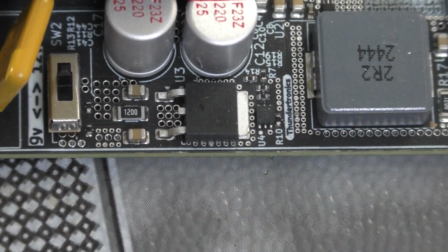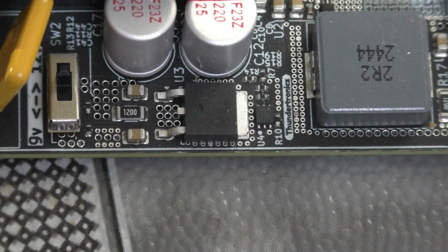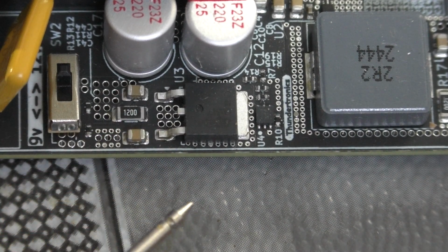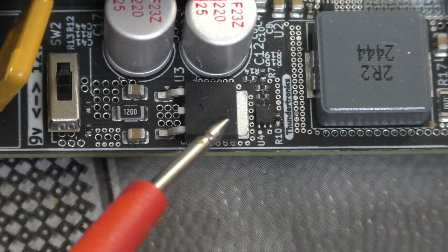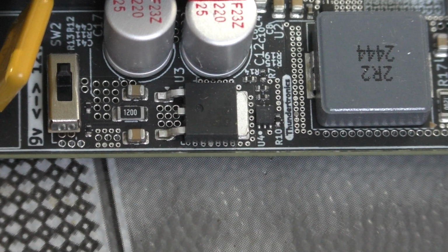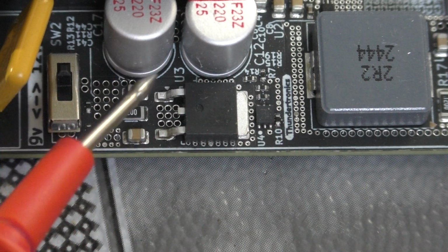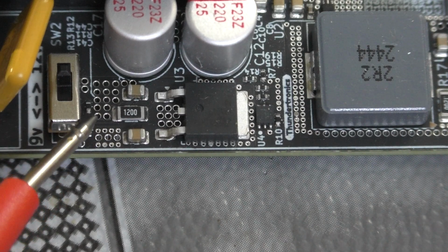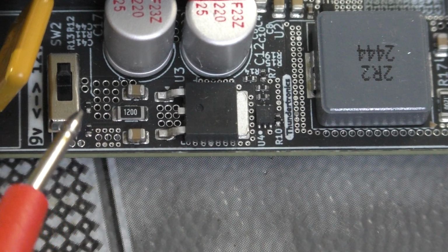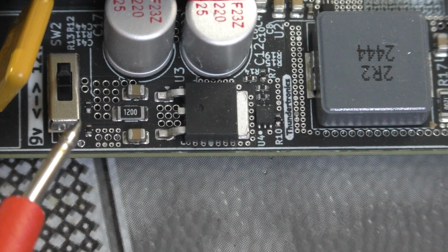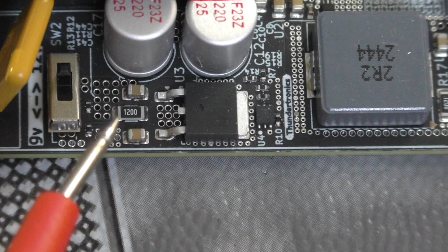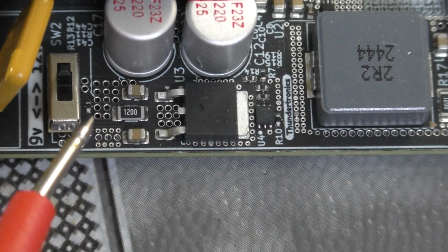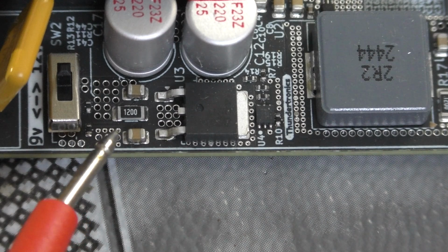Okay, so we talk now about practical implementation. This is one of the early prototypes of one of my upcoming products I made. I needed a 9 to 12 volts rail, so I used an LM317, as you see right here. This is the input capacitor, and that is the output capacitor. This is a 120 ohm resistor, as well as these two here, small ones, which are other feedback resistors, because they are going to be switchable between 9 and 12 volts. So I needed the upper resistor to be switchable, but basically the same thing.